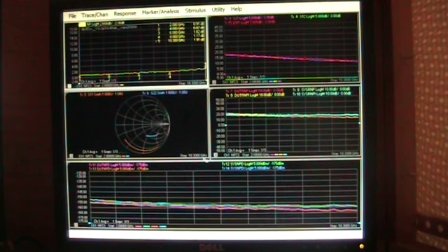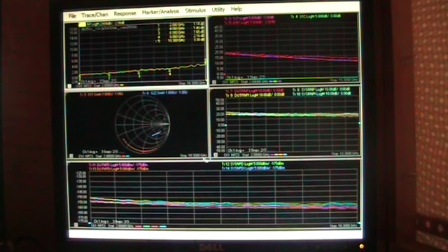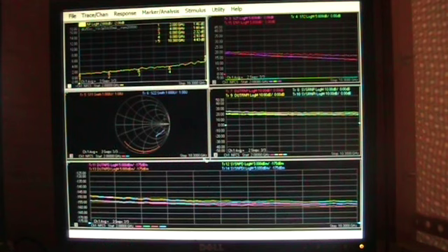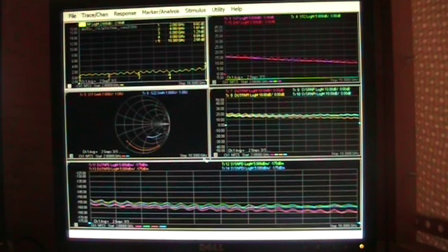And then the code is actually stepping through very slowly and running this on all of the bias conditions. I should have let that run here. So go ahead and step through that. Once it's completed the fourth bias condition, this is where the fun begins. We'll go ahead and move the tuner to a new position. It'll look a little weird here for a moment. The tuner will move and the de-embed file that goes with it will be presented. And now we'll take another measurement in this new position.